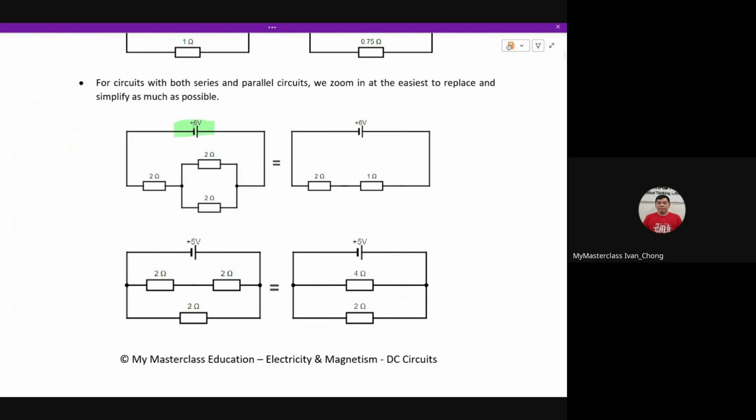Problem is, if you draw this to the dot over here, all of these are total current. All of these are current 1. This is current 2, right? So now you have a series and a parallel. To avoid the confusion, you see this yellow and this blue color part. If you simplify it using your effective resistance formula, 1 over 1 over 2 plus 1 over 2, you end up with 1. So basically, if you are finding current, you need to simplify it and solve it.